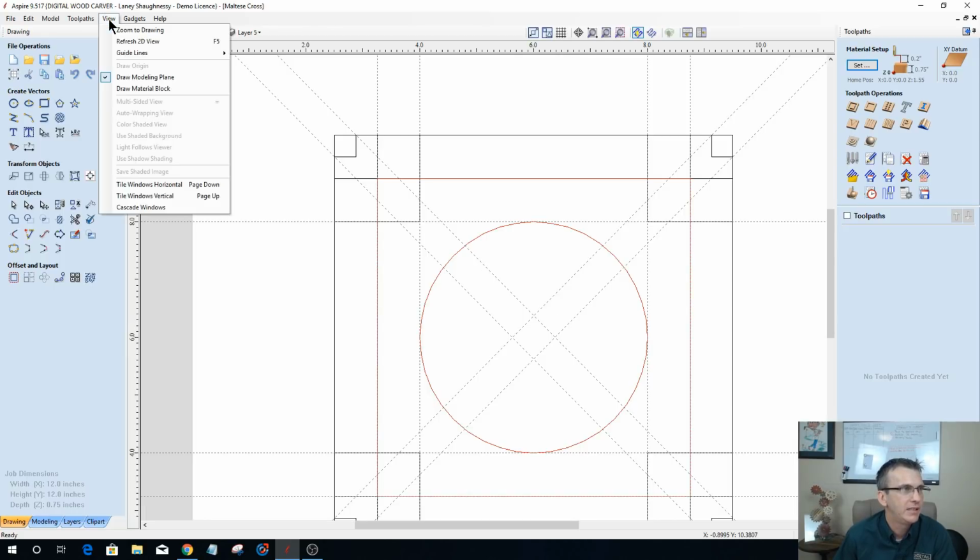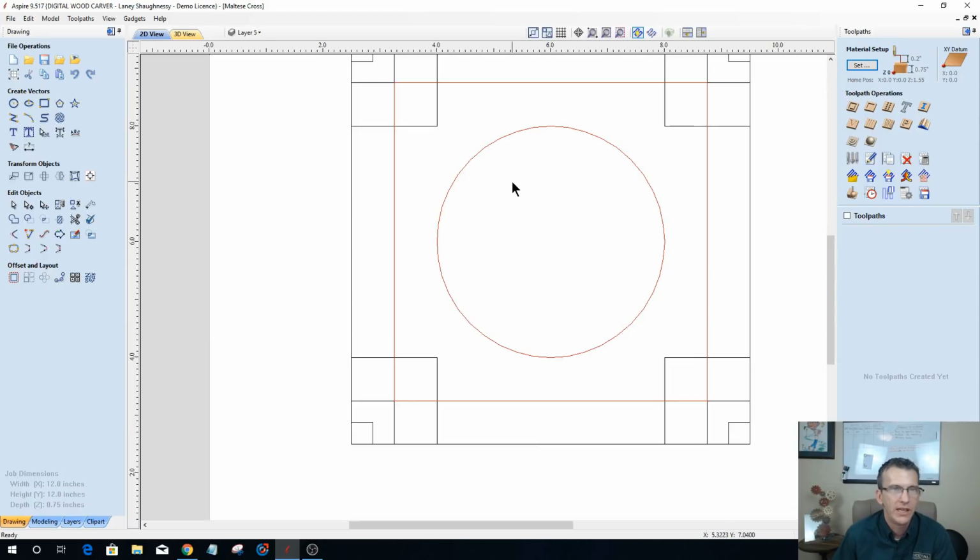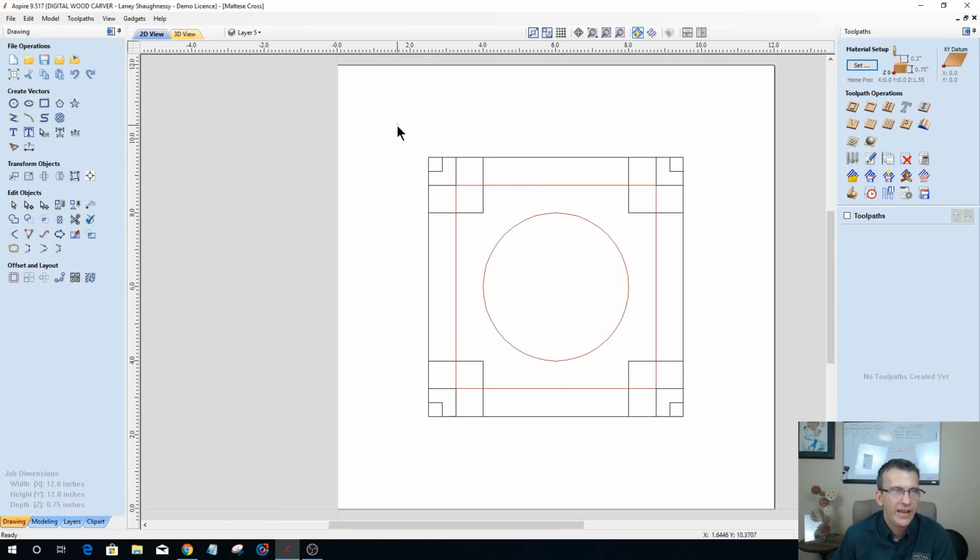So we can see those lines. Let's turn off our guides. Let's turn off the guidelines for a minute. And you can see what we have here is a circle, a 4-inch diameter circle. And then we have a rectangle, and the corners of that rectangle are snapping to those 3/4 inch squares that we started off with. So we have a 3/8 inch square. That helps us with our diagonal lines. Our 3/4 inch square gives us the layout of our rectangle. And then our 1.5 inch square gives us the diameter, edge to edge, of our circle. Okay, so that's how I use these boxes here.